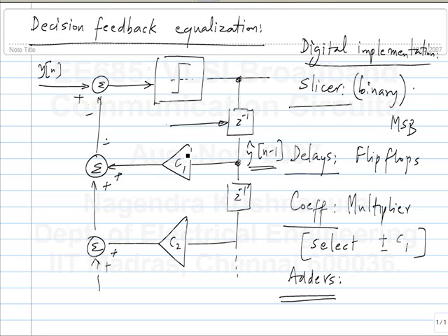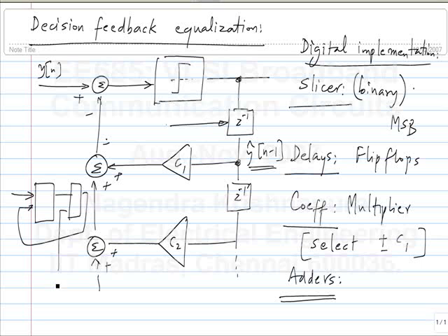But if you have done a course on digital IC design, you know that you have a loop like this, which is essentially an IIR filter. Whether it's IIR or FIR doesn't matter. You have some input, some logic being performed, and some storage and feedback. And for this to work with a certain clock period, the delay of this has to be limited. So it's the delay of this plus the clock-to-Q delay of the flip-flop and the setup time of the storage element. Okay. How many of you are taking digital IC design this time? Okay. So I think you do understand what's going on, right?